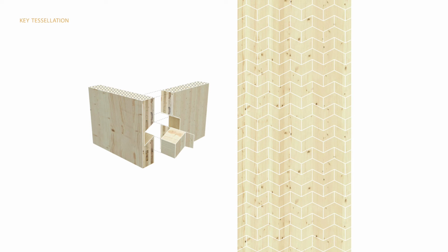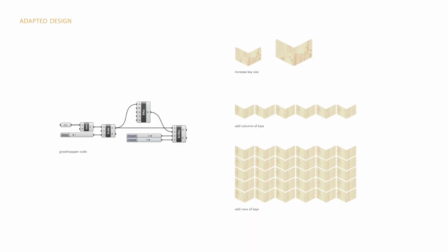This chosen design uses the most successful qualities from the previous prototypes: simplicity and a wedge-shaped center, combined with the proportions of a traditional dovetail. This design was then rationalized and developed to create a simpler cutting path and the ability to parametrically alter the design based on project-specific requirements. This means that the number of keys and the size of the keys can change with each project, with very minimal interference or changes to the design.